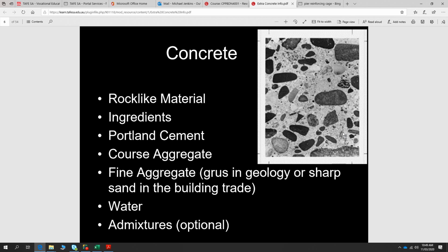But let's say you're doing a burnished concrete floor, where you have a really nice smooth steel trowel finish, like a Bunnings floor. Anybody taking notice of floors in Bunnings warehouses? Really smooth, dark grey concrete floors. That's done with just general purpose cement. You don't want any slag in that, because if you use a cement powder that has slag or fly ash in it, it gives it a greenish tinge and it doesn't darken up nicely. So this concrete out here, I think that might have been with slag or fly ash in it.